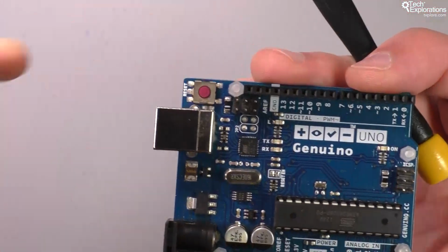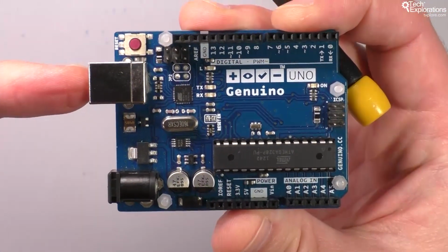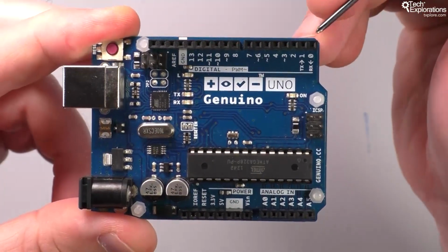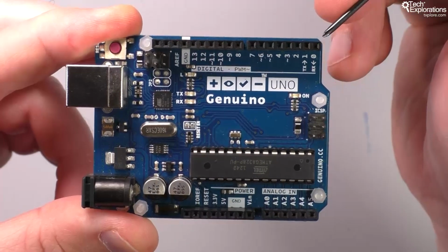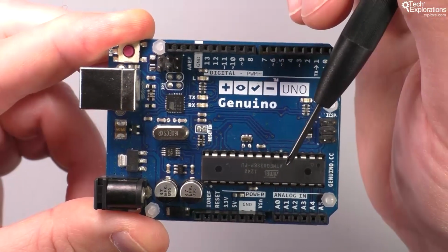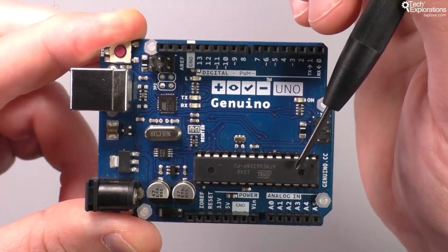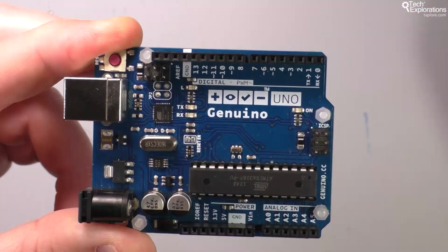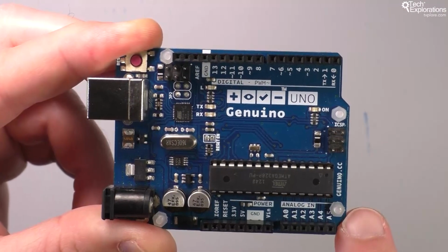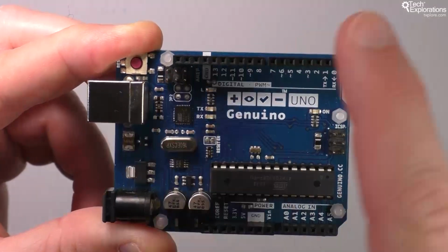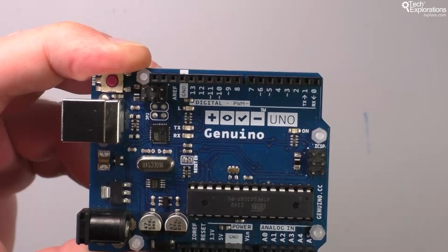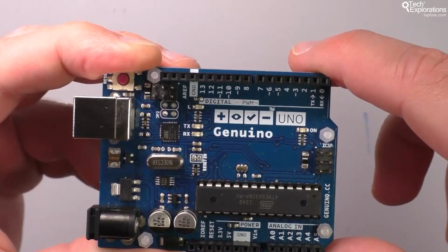So that means that when your computer is connected to your Arduino Uno via USB, it's actually these 2 ports that allow the USB controller to communicate with the Atmega 328P on your Arduino Uno. But when your computer is not communicating with your Arduino Uno via USB, these two pins are available for other devices to use in order to communicate with your Arduino.